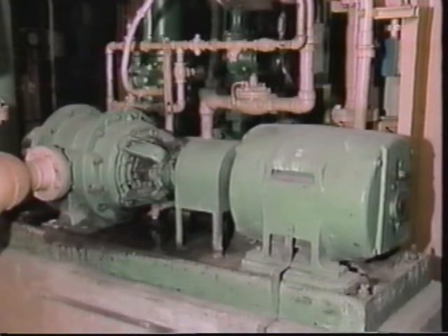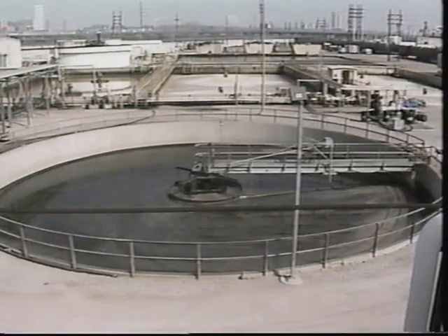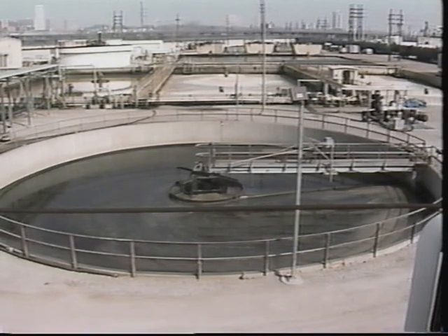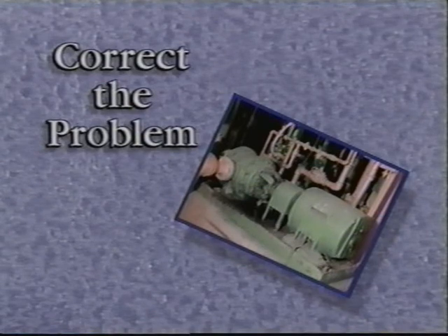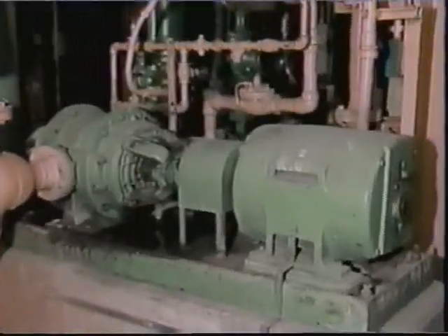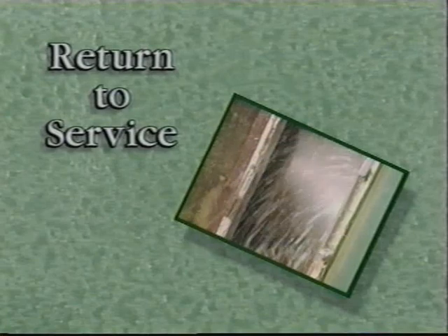It's discovered that a pump for the spraying system has shut off, so water is not being pumped to the screen. This is determined to be the cause of the high sludge blanket level that was first detected in the secondary clarifier. The problem with the pump has to be reported, and the pump will need to be repaired. In this system, however, there is a standby pump that will work until the other pump is repaired. With the standby pump on, the screen cleaning system is put back in operation. The sprayed water keeps the screen free of solid debris that could otherwise be carried through the wastewater treatment system.